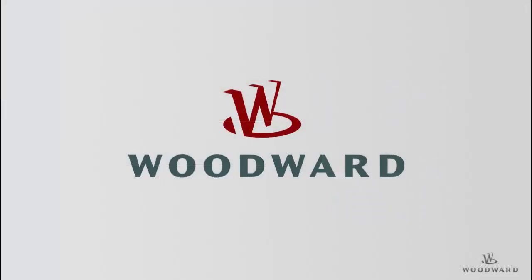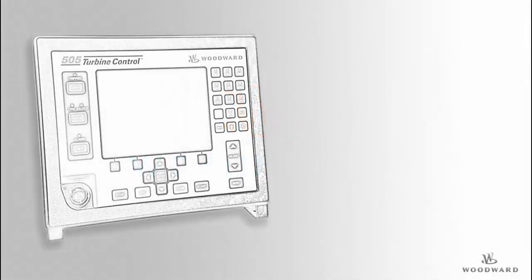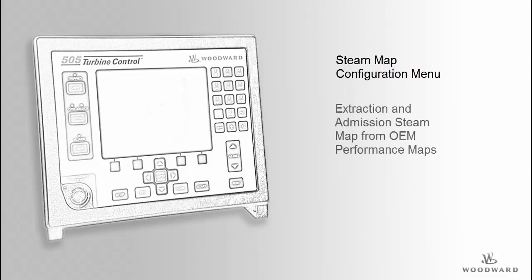Hello, and welcome to this series of 505XT steam turbine controller tutorials. In this tutorial, we will first overview the steam map configuration menu. Then, we will review how to program the 505XT extraction and emission steam map from OEM performance maps using the steam map configuration menu pages.